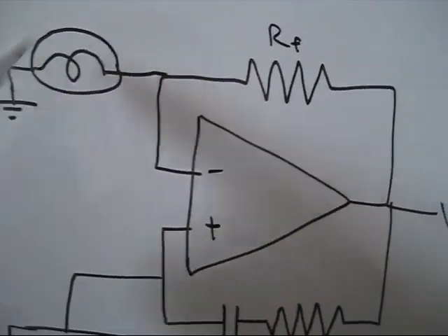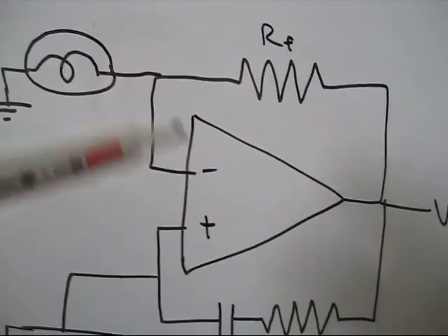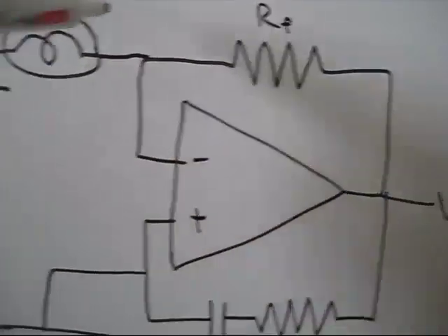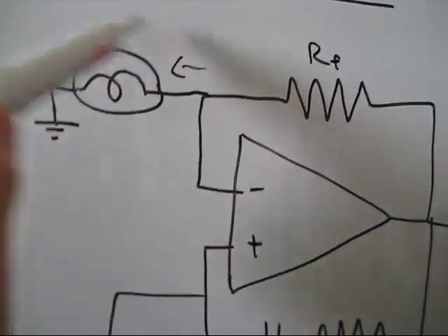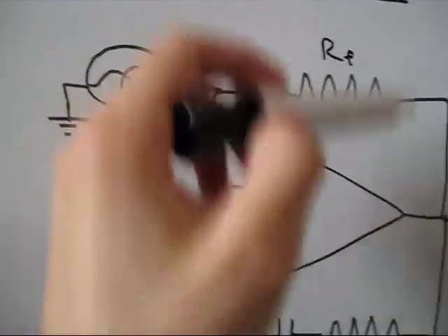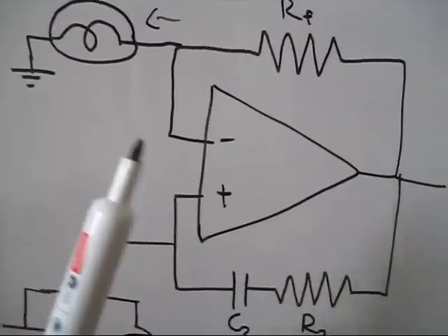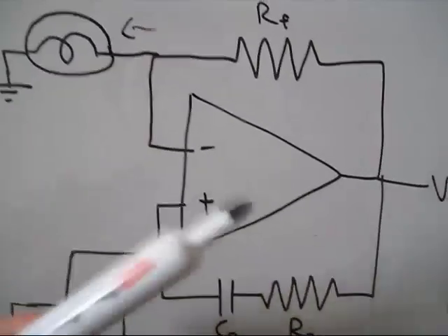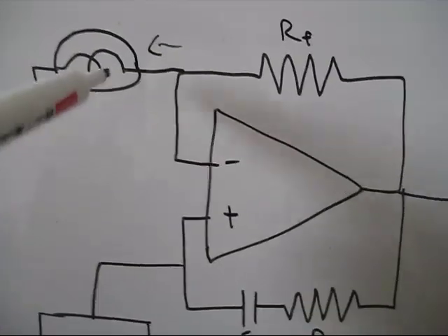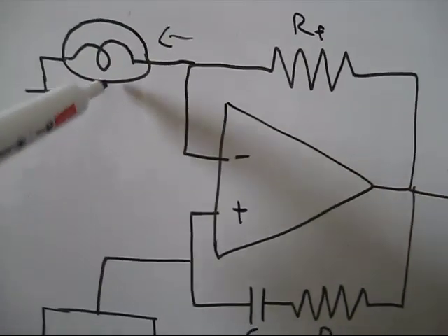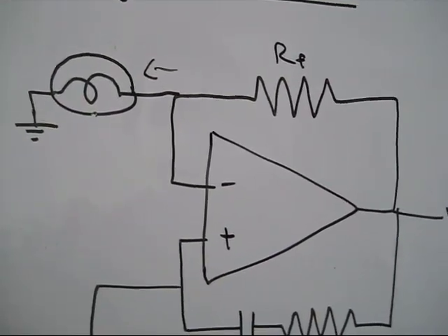So at startup, it'll be low, so the gain of this circuit is going to be very high. Then it starts up, but as current flows through, that's going to heat up and decrease the gain of the oscillator. Because now you don't need all that gain anymore. Now you want a proper oscillator to continue to function, so you want to decrease the gain. So this was his way of introducing amplitude stability, which was actually a really neat idea.